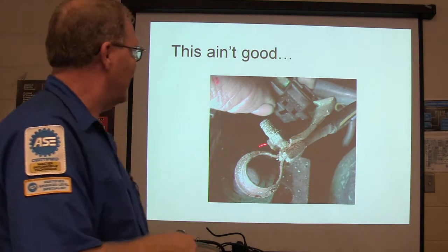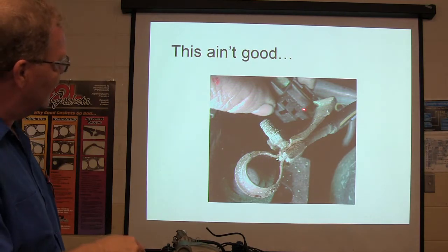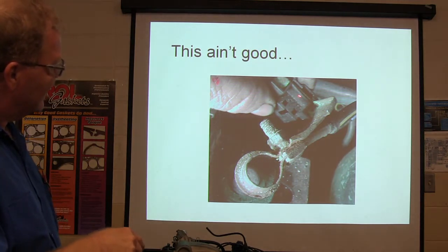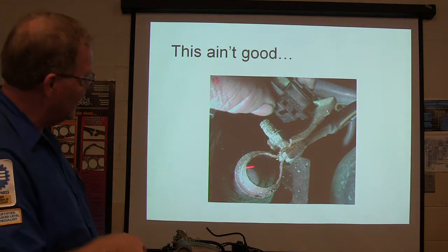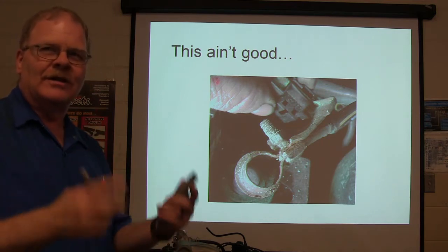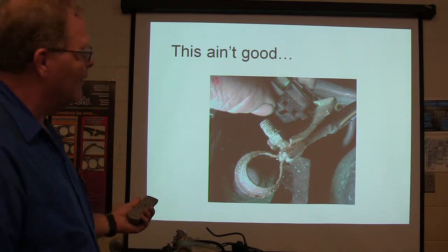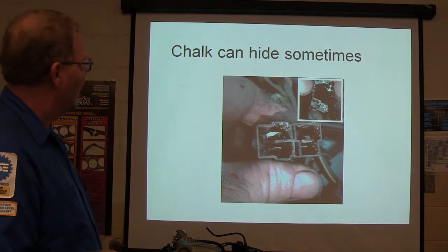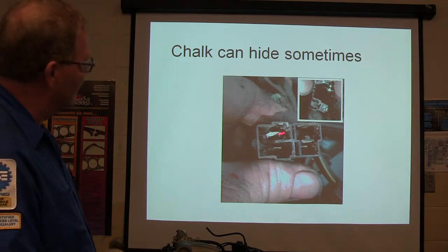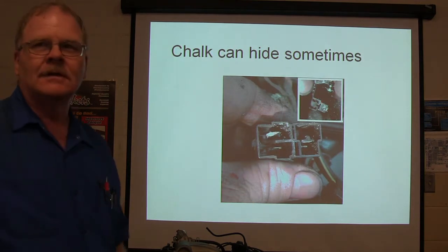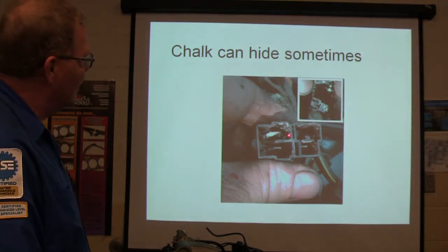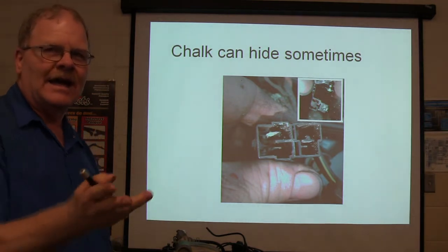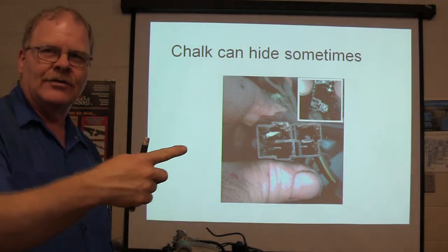What is that? That's a battery terminal. And coming off of here is a little connector where all the grounds are supposed to hook up. You see how crummy that looks? These batteries, sometimes whenever they get old, they'll leak between the lead post and the plastic part of the battery. When you unplug that little ground terminal, I'm seeing all this chalk in there. I'm seeing hidden chalk. These grounds are basically the ones that are feeding the data link connector, and also ground the speed sensor.